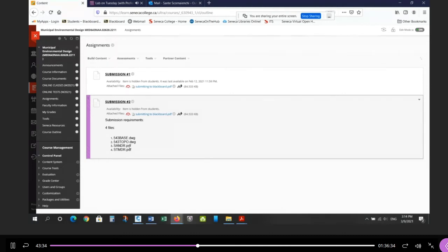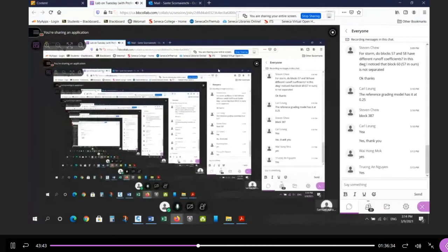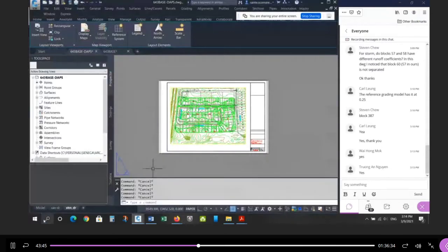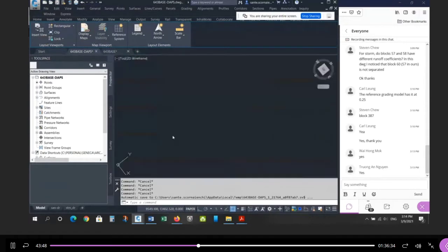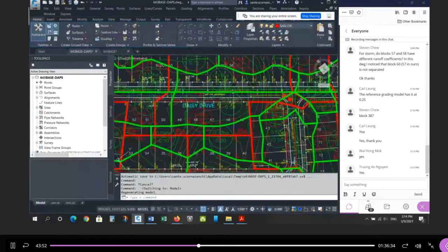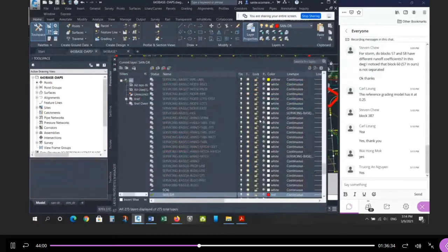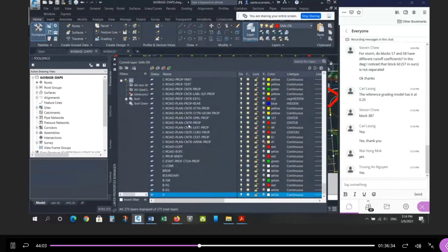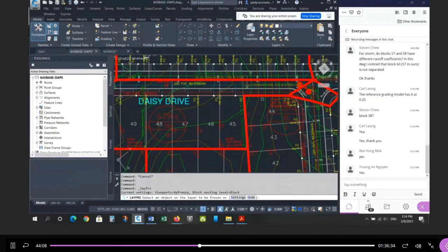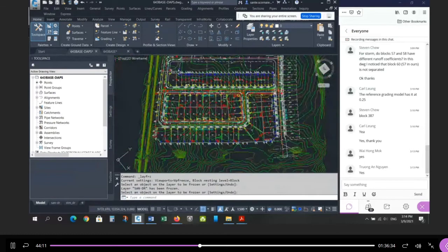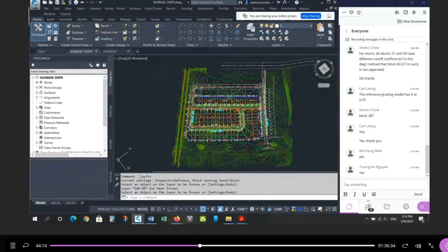When you print those, and you're done, if you go back to the drawing, back to the model space, once you've printed, you can actually freeze the drainage areas again, right? So then freeze. I don't need to see the storm and the sanitary drainage areas in this file. So after you print, you can come back and freeze them. You can't freeze them when you're printing, otherwise you won't see them, right? The corridor is frozen and so on. So that's what I expect to see.